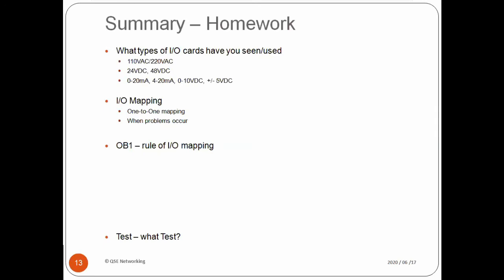So when it is at 0, it's actually giving you 4 milliamps. So when you have less than 4 milliamps, you know there's a problem. The sensors are either faulty or the wire is broken. And you can also get a 1 to 5 volt DC. The plus and minus is for things like some adjustment rheostats or buttons that you use, but that's another day.